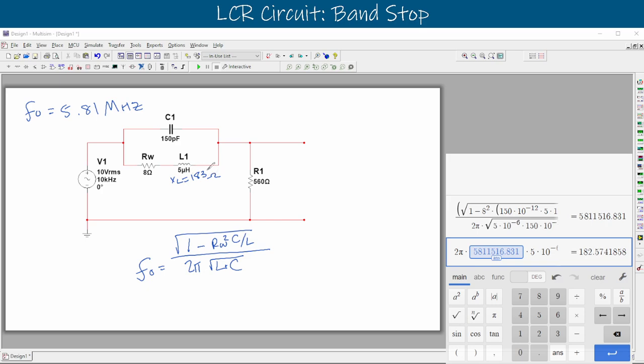And that's the resistance of our inductor, right? We call that the inductive reactance. So next we can use that to determine our Q factor, and that's going to be the quality factor between our linear and nonlinear components, specifically our winding resistance, because it's in the same branch as our inductor over here. So we'll say that our Q is equal to our XL divided by our winding resistance, RW.